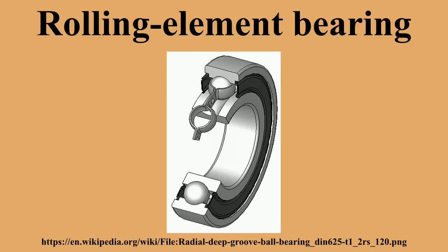7208. Digits 1 and 2 together are used to define the inner diameter, or bore diameter, of the bearing. For diameters between 20 and 495 mm inclusive, the designation is multiplied by 5 to give the ID, e.g. designation 08 is a 40 mm ID.